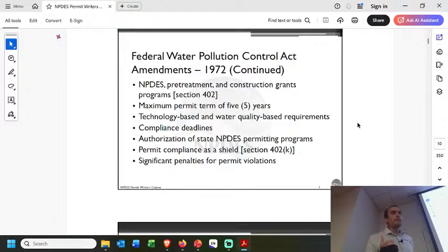You can have, in some cases, technological based, where we know that if you had, let's say, common petroleum products, that activated carbon filters are the way to go. And so we can prescribe, okay, if this is your industry, you've got a groundwater cleanup that was contaminated by a gas station, for sure you're using activated carbon, and this is how you're doing it. You have some option of saying two activation column tanks. Here's the typical operation. You can design it exactly how you want, but you're using carbon, a technology-based treatment. And we know that it works. We know it works so well, and that we know that these are the contaminants. So there are some cases where a technology is prescribed instead of an effluent limit.